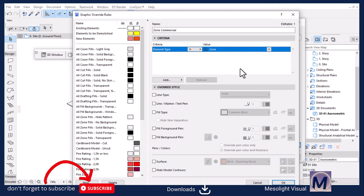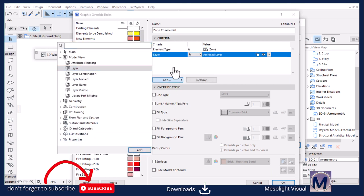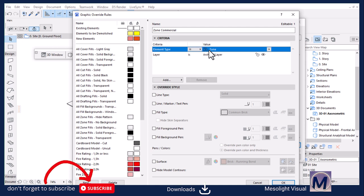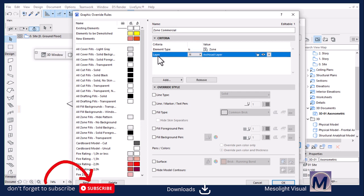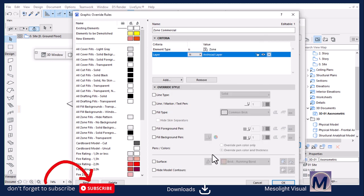Where is the zone tool? And then we're going to add another criteria for layer, because there are also zones for residential, but we don't want them to be affected by this rule. So it's important here. We're going to use the layer to further filter that. So let's find the layer for commercial, and then we come down here to override.